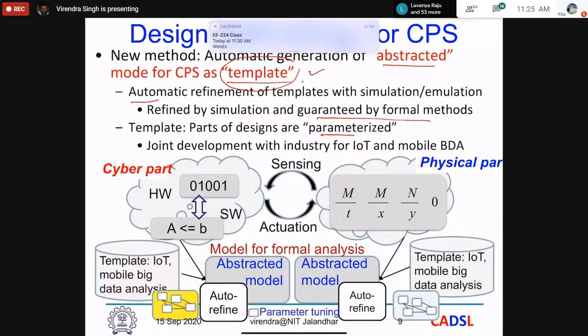If I do that, then my speed is not governed by the speed of the FPGA, but by the speed of the interconnects. This may drop from a few hundred megahertz to something like some kilohertz. That means thousands or tens of thousands or millions of vectors I can still apply per second. So that is significantly faster than the simulation process, three to four orders of magnitude faster, but still that cannot cover all the cases within a reasonable time,